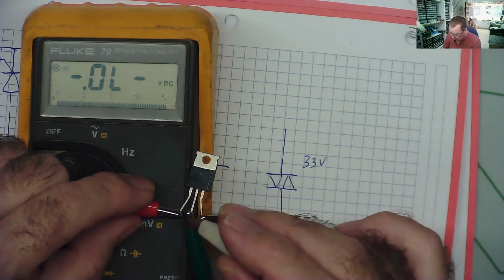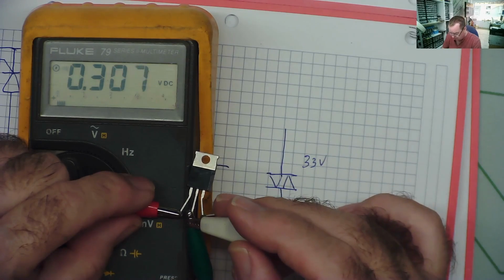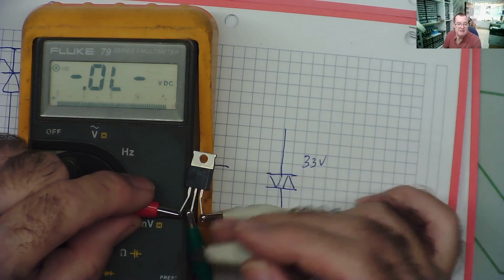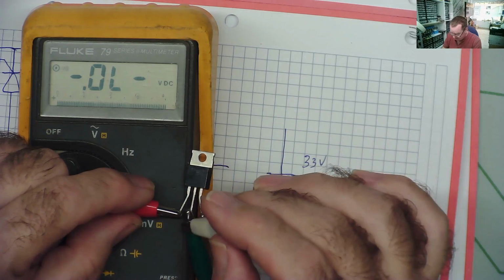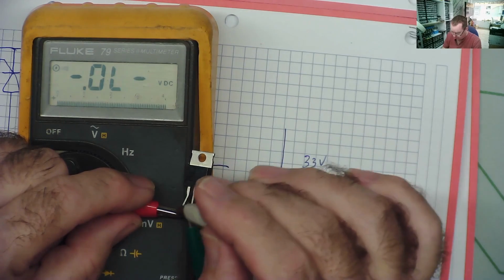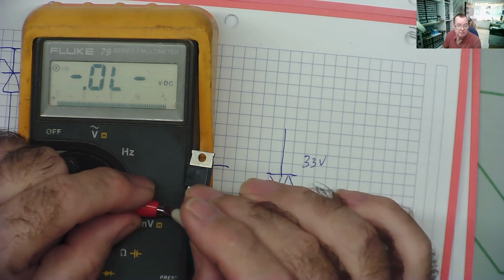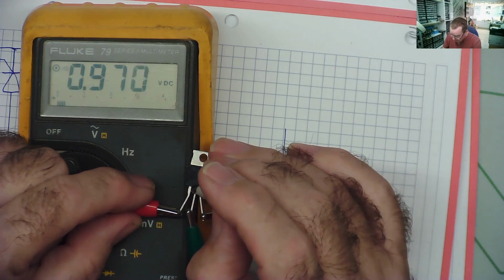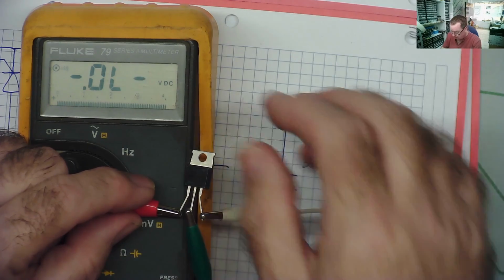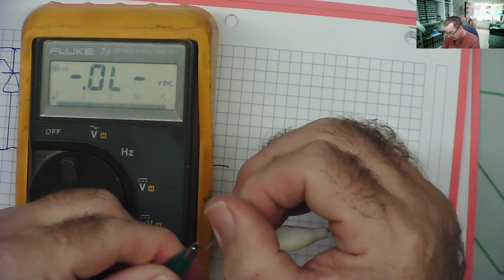You notice this one isn't latching because it's a higher powered device. The threshold current must be higher. You could make it latch, but you'd have to use something like a little power supply, battery and LED, to give it more current if you wanted to test it that way, okay? When you go to the other one, nothing happens. So only connecting to this main terminal will it switch on. Now let's reverse the wires. So the gate stays where it is.